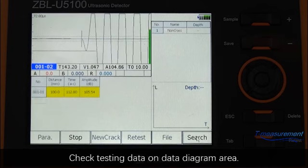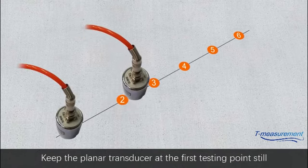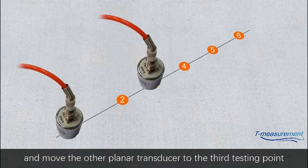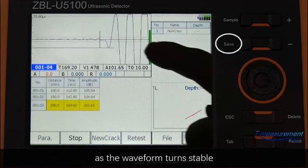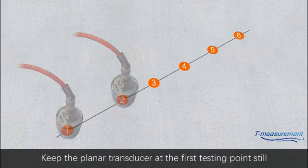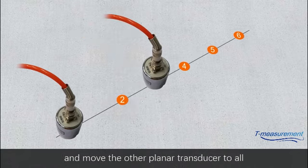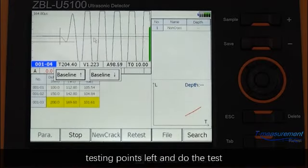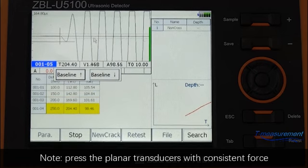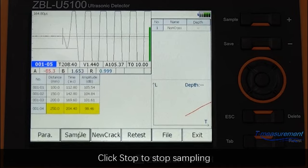Check testing data on the data diagram area. Keep the planar transducer at the first testing point still and move the other planar transducer to the third testing point. Adjust the waveform and press Save button as the waveform turns stable. Keep the planar transducer at the first testing point still and move the other planar transducer to all testing points left and do the test. Note: press planar transducers with consistent force. Click Stop to stop sampling.